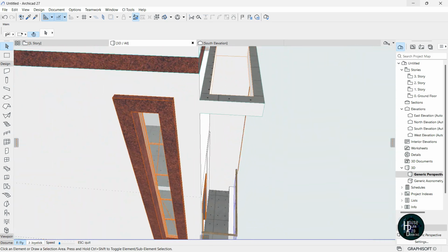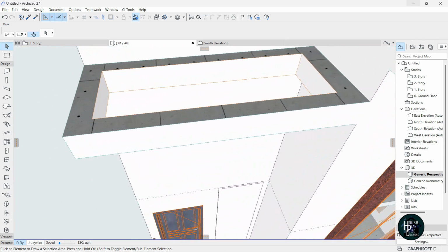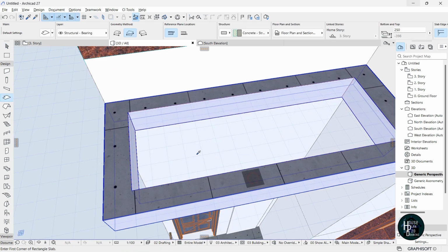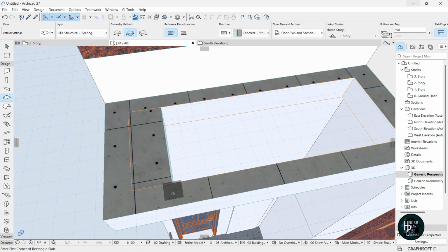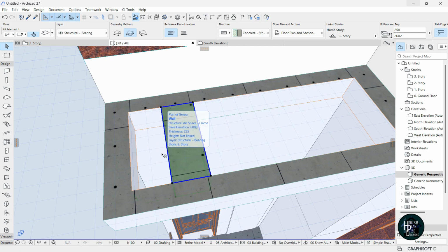Now the next thing I want us to do is try and make a little bit of design inside this. What I mean by that is, just hold down Alt, select this slab, pick a point here, drag it to meet this point here, and press Ctrl D. Click this point and move it a little bit outside, maybe around here. Once you do that, come here and change this to be around 100, click enter.